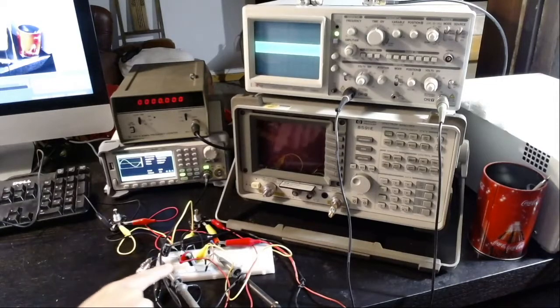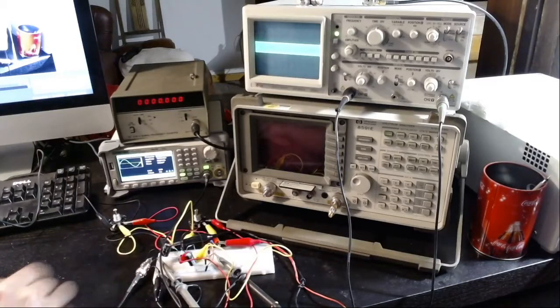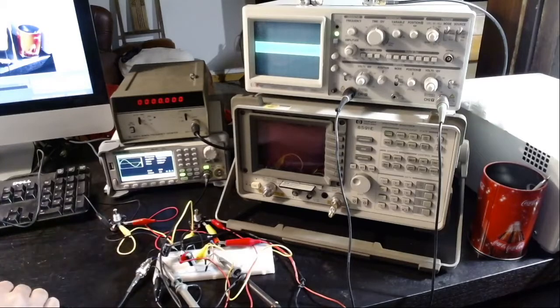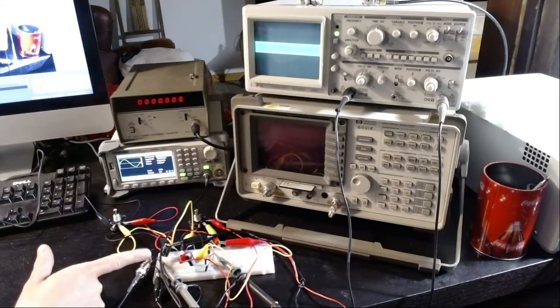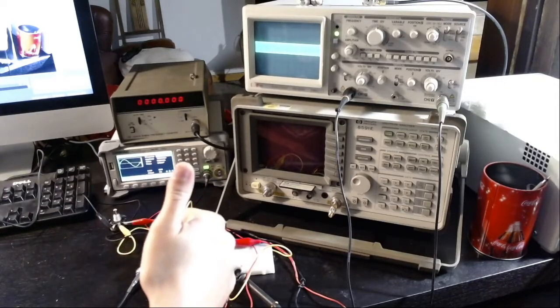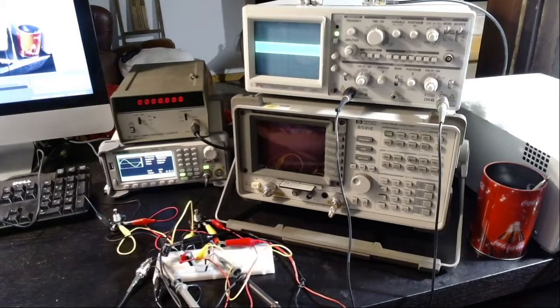But that's probably because in the breadboard there is capacitance everywhere. So high frequencies find a way to ground different than what is expected, but anyway, it's not very much attenuated. So this means that this amplifier is respecting these constraints up to a certain degree of having a good 50 ohm input impedance. So these were the three constraints I had on this amplifier: 1, to amplify, 2, to only amplify low frequencies, and 3, to have a 50 ohm input impedance. And with this said, we'll now move to the software to show you how LTSpice works.